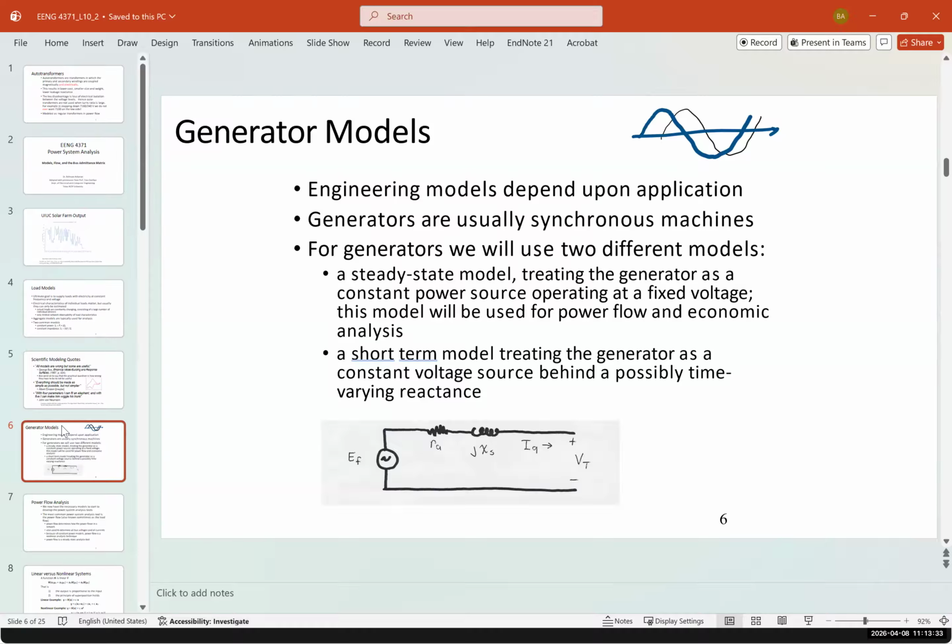So if I connect this generator to this grid, what happens? It can cause huge damage. Sometimes the phase shift is even 90 degrees, so when one is positive, the other one is negative. So you're going to have a huge problem. So what they do is use a synchronometer. I don't know if you see it. It's like a clock, and it shows the difference in the angle.